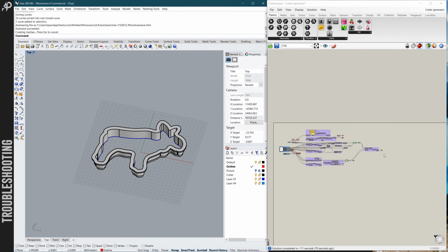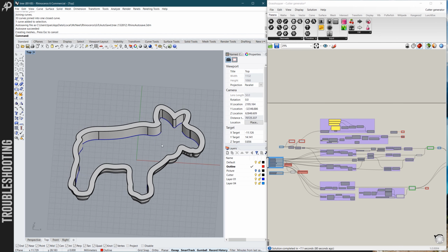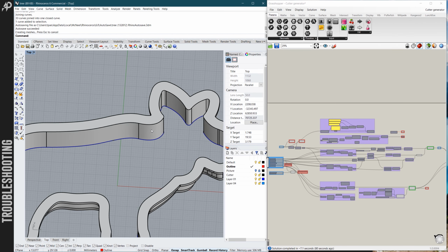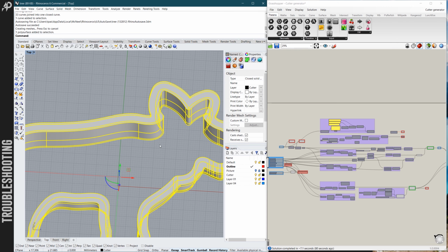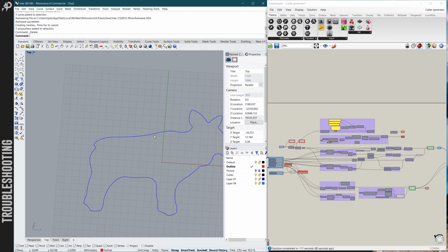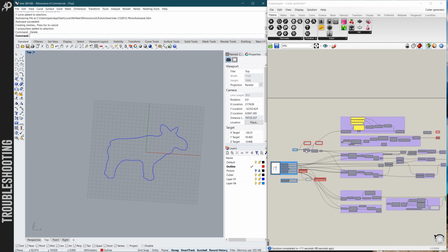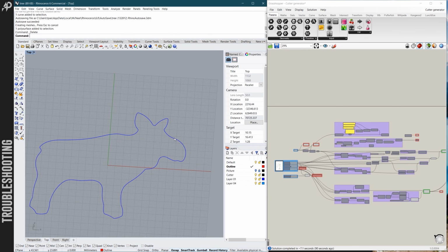And there is one more error that might happen and that I want to cover, and it is about curve seam. Each closed curve has a starting point which is the end point at the same time, and from that particular point I am extracting the cross section of lower chamfer that I drag around this rail.